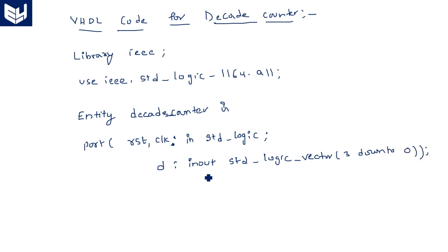So we have taken clock signal and reset pin. The clock signal is used to change the state, or for incrementing each state, and reset is to reset all the flip-flops to the beginning state, or whenever you want to reset all the pins to zeros, you can use this pin. And D is acting as either input or output.